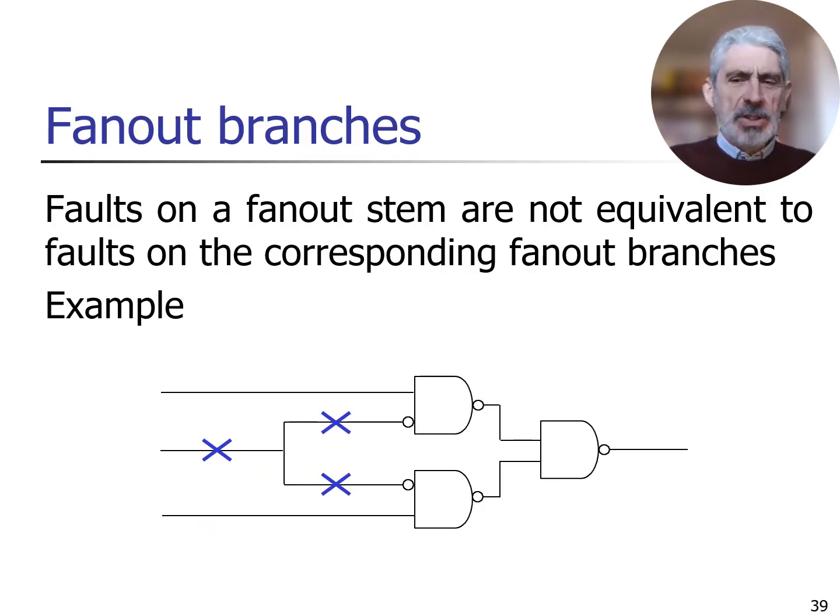The circuit which we were using to provide an example of usage of the stuck-at fault model was a simple tree circuit. And clearly in real circuits it is common to have fan-out branches. Now with fan-out branches the situation is a little bit different because we need to consider both the faults on the stem line and the faults on the branch lines. And we need to consider all of them because they can be tested by different sets of test vectors.